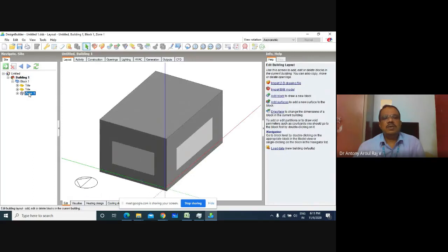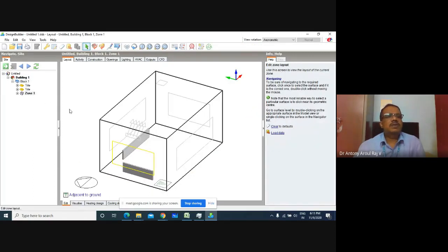So here, when I select the zone, you can see the various components of the zone itself. The room is already there, and I think several boundary conditions are already given for this problem. We have a supply here, like a split AC, from where the throw moves up, and here we have an outflow or vent. The walls will be at low temperature, or whatever temperature is given as per the boundary condition. So this is how the domain will be.